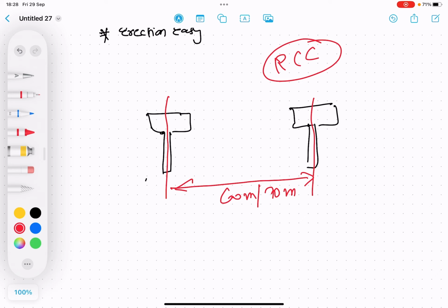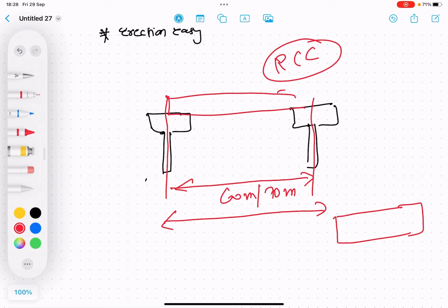And if the span length increases, then the thickness of that element also increases, as it has self weight, and apart from the self weight, the metro will run over it. So the thickness will also increase. Okay, and as self weight increases, thickness also increases. In such a case, casting an RCC structure or erecting the RCC element directly on these piers is not possible. So what we do is steel erection.